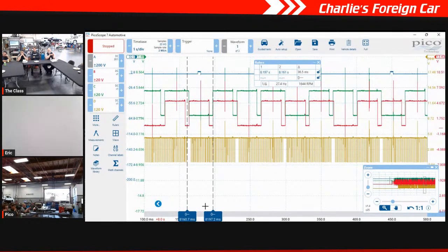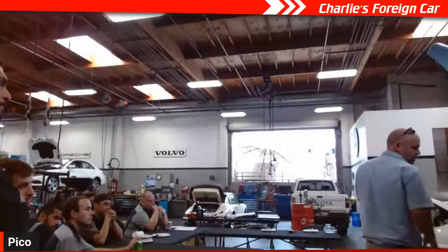It was right between the two mounting bolts on the front. You had to kind of look low. It was 190 degrees right here. On the exhaust it's only 150 degrees. So 40 degrees less. So we are assuming we don't have any oil flow. So there's no oil running through the solenoid. The cam timing's not moving.